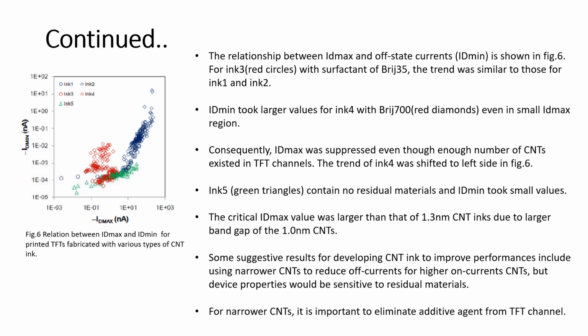Narrower CNTs are promising to reduce the off currents for higher on-current TFTs, but device properties would be sensitive to the residual materials. It is important to eliminate additive agents from the TFT channel entirely when narrow CNTs are adopted. Further development and investigation for CNT ink and fabrication technology, such as a surfactant removal process, are required.